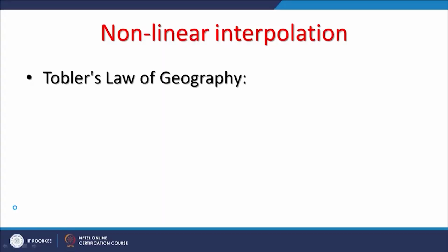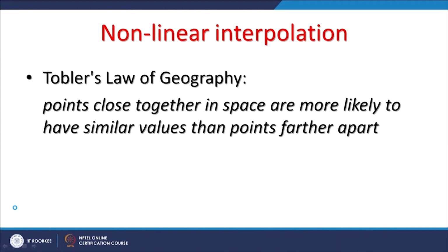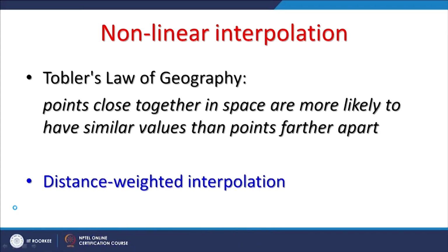Anyway, now we come to the other type of interpolation techniques, which is considered non-linear, and which is again based on Tobler's law of geography. It says that points close together in space are more likely to have similar values than points farther apart. Using this concept, interpolation techniques have been developed which are based on distance weighted interpolation.